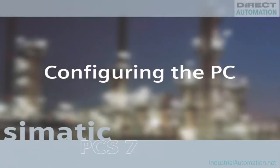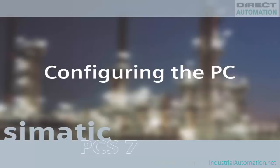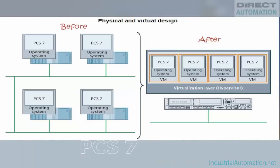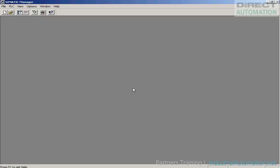In this sequence, we are going to show you how to configure your computer before you actually start configuring the SIMATIC PCS7 application. This step has to be carried out once at the beginning of the configuration phase. It is basically required to define the communication links between the automation components and to create the project itself.